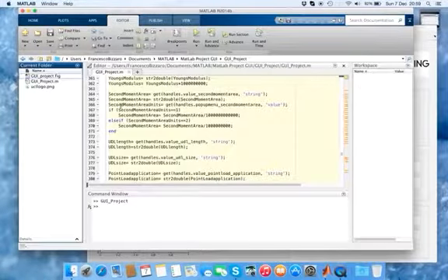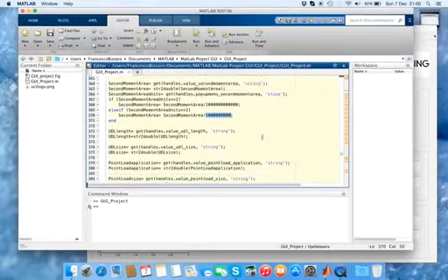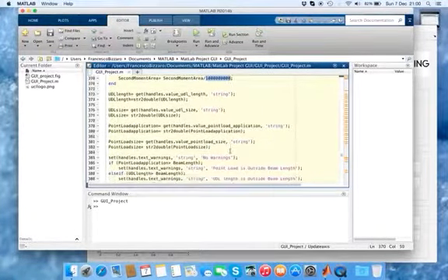I therefore say that when taking the values from that text box, converting it into numbers, I also say that if that second moment area units of the pop-up menu is position 1, then the second moment area should be divided by a certain number. If it is 2, it is divided by another number to equalize all the units into meters, which we are using in the calculations further on.